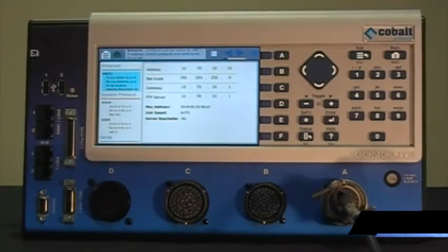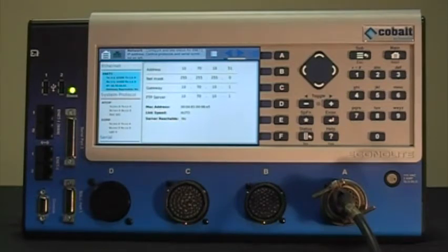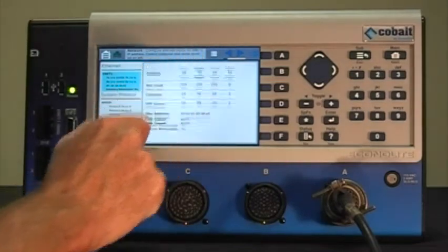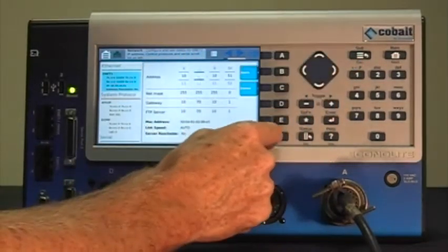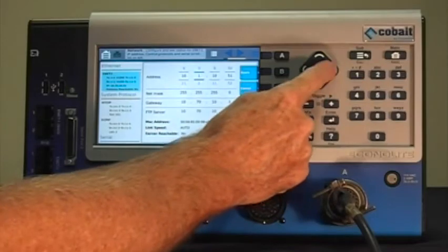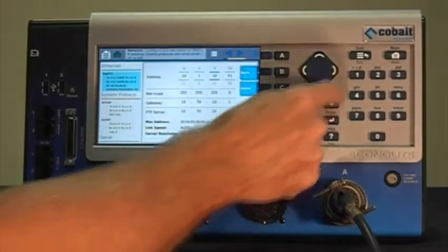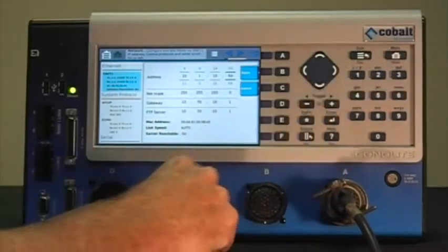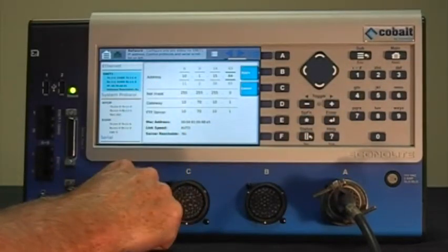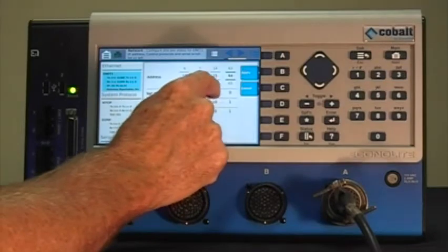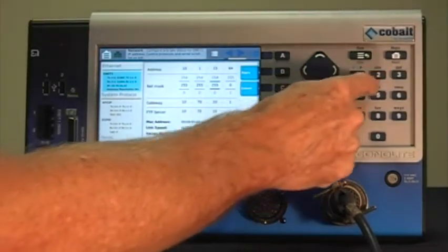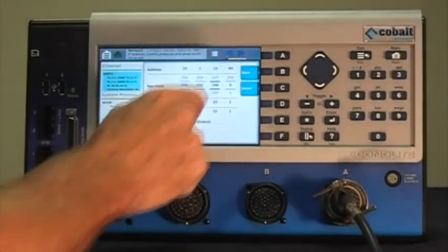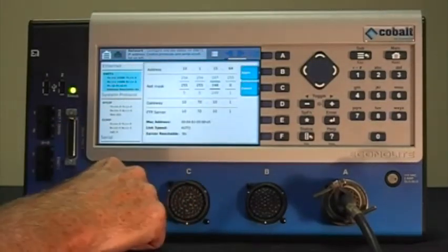Let's say we want the controller's IP address to be 10.1.15.64. The address field here, we want 10.1, so 1, and I can use the scroll wheel here, tap over, put in 15, and lastly it'll be 64. Then for the net mask, I'm going to want 255, 255, 248, 0. And you notice I'm not hitting apply yet because I can do that at the end.